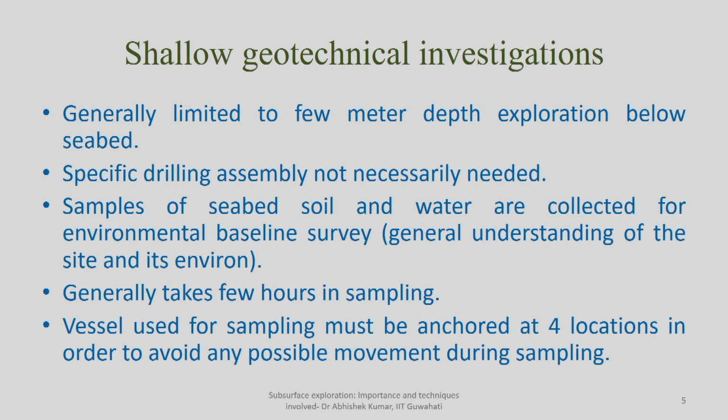Then shallow geotechnical investigation. These are generally limited in depth. Whenever we go for shallow geotechnical investigation, as I mentioned, the depth is generally limited to a few meters, again depending upon the method you are using for sampling and the characteristics of the medium at the sea floor.